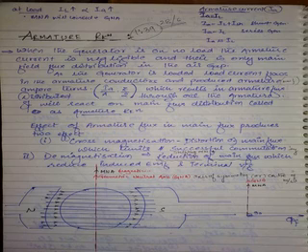So, in the machine, there is stator, there is rotor, there is an air gap of 1 mm. In this air gap of 1 mm, the main flux, working flux, is uniformly distributed throughout the periphery of the armature. If there is no load, there is no problem in the machine. Problem comes with the load, with the current. Once the machine is loaded, the armature conductors carry load current. As the load is increasing, the current flowing in the armature conductors also increases.